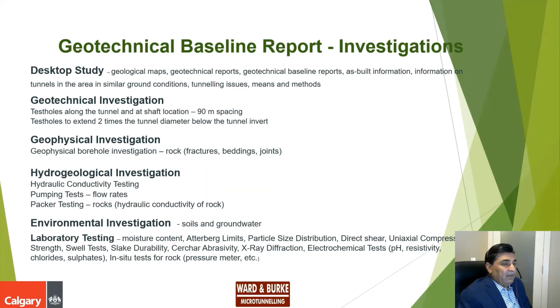Then we can do hydrogeological investigation, and with that, we measure hydraulic conductivity of soils, do pumping tests to determine flow rates, and then we do packer testing to determine hydraulic conductivity of rock. Environmental investigations are done to confirm if the soils are contaminated or not, because if they are contaminated, they have different disposal requirements.